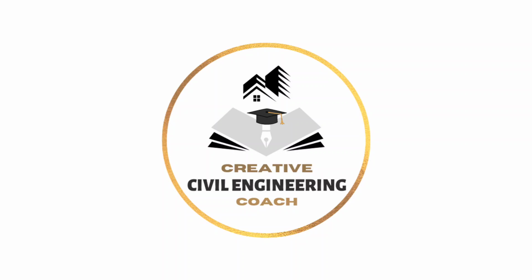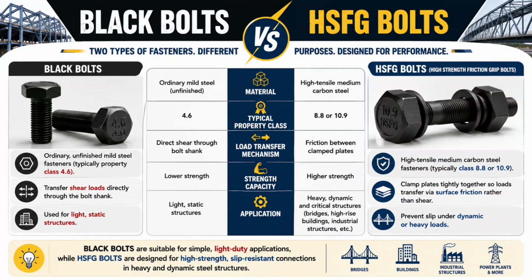In this session, we'll discuss the two important types of bolts used for steel design connections. The two types of bolts used for steel design connections are black bolts and HSFG bolts. Here, HSFG stands for High Strength Friction Grip Bolts. Black bolts are suitable for simple light duty applications, while HSFG bolts are designed for high strength, slip resistant connections in heavy and dynamic steel structures.